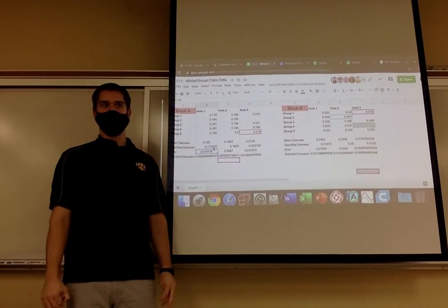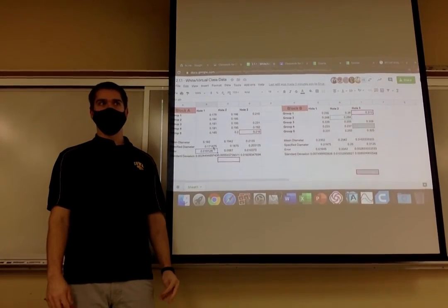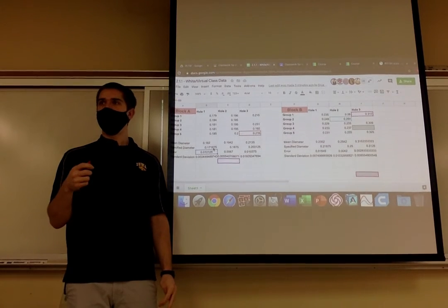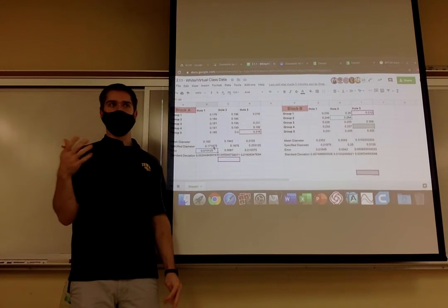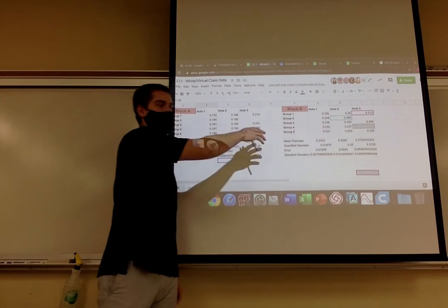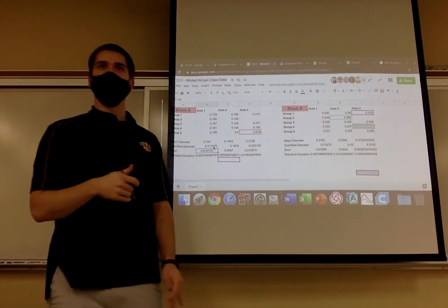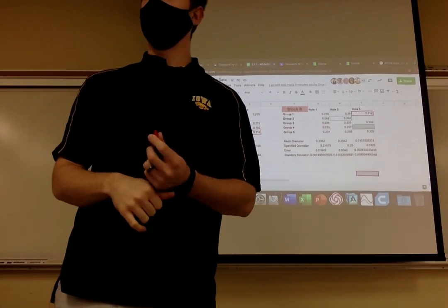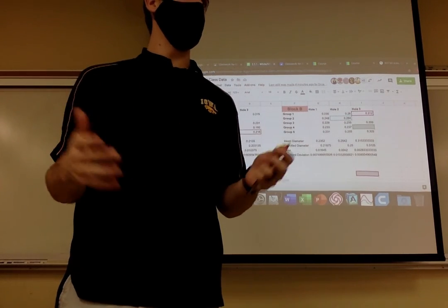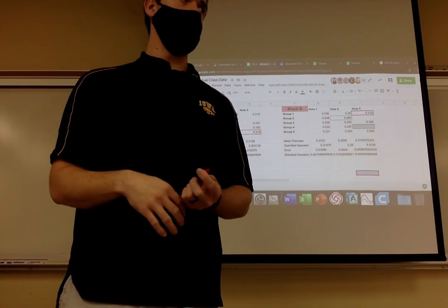That's why we have tolerances. We set tolerance because we know you can't make things exactly, and you have to figure out how much room for error you give so that your design will still work. Depends on the design, the application, safety risks, etc.